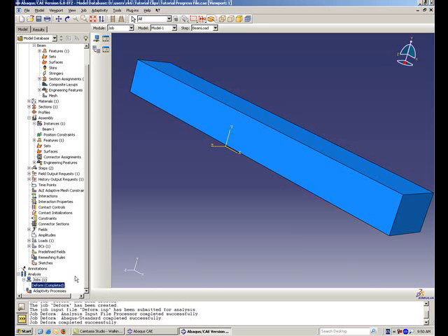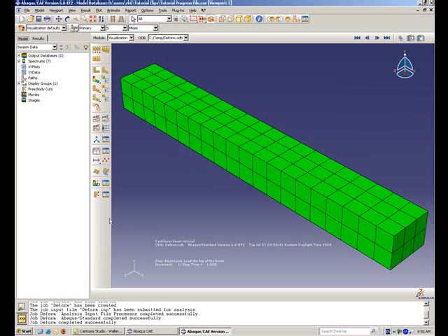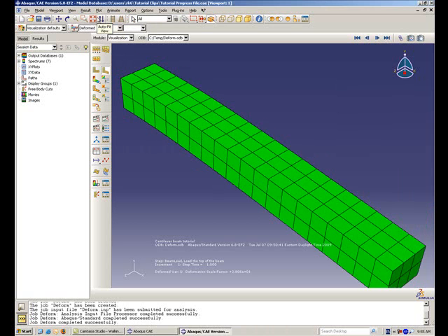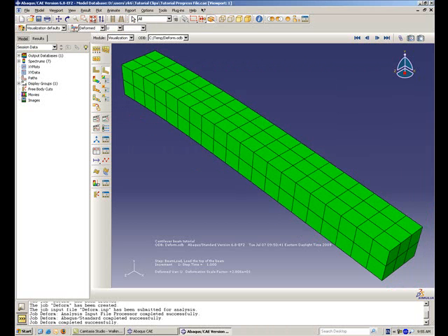When the status says Completed, right-click on Deform and select Results to enter the Visualization module. To see the deformed beam, simply go to Plot in the main menu bar and check Deformed Shape. Click the Auto Fit tool so the entire model is in the viewport. Now go under Plot to Contours and choose Undeformed Shape to view a contour plot of the stresses on the beam.